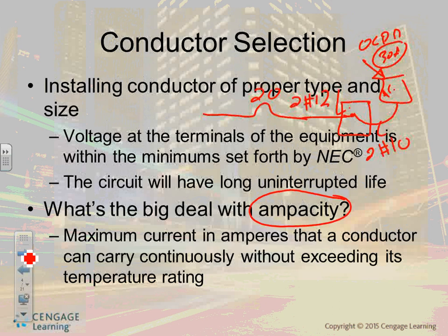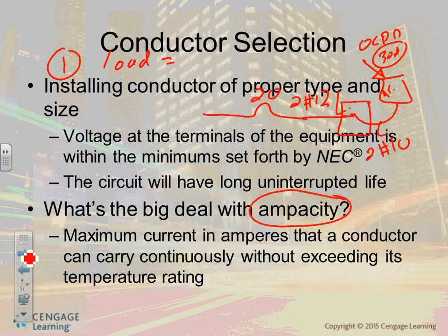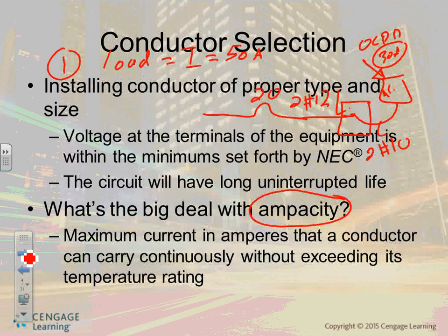I always tell people, when you find the ampacity of the conductor, take three things into consideration when you size the ampacity. You will never go wrong. Write them down. The first thing you need to size for, guys, is the load. The load, like in amps, like 50 amps. That's the first thing you need to take into consideration, the actual load. Sizing the ampacity of the conductor, you have to take the load into consideration. Then underneath it, ask yourself, is it continuous or not?